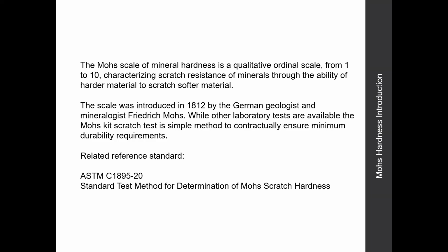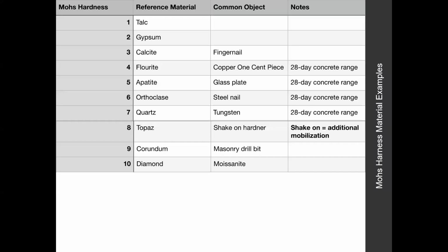The last thing I think it's important to measure here too is Mohs. For those of you who are not familiar with the Mohs mineral testing, this is not on the micro scale. It's a handheld stylus, and they're of varying degrees of hardness. They start, gosh, all the way from talc all the way up to diamond at a 10. These are very simple measurements to take, whether it's a third-party engineering firm or the design engineering team. Most concrete that isn't cured very well, or is so-so cured, is going to be somewhere at a 5, maybe as much as 7 if there's some wet curing, by about 28 days. And we were measuring 7 to 8 Mohs by day 1, the end of the day.